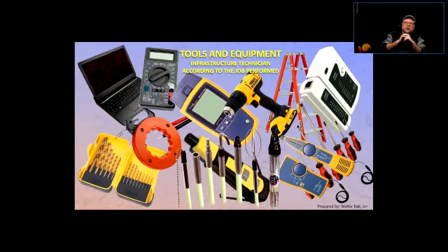Now, when you're talking about bigger holes, like 3/4 of an inch or 1/2 inch, and the concrete is hard enough, then even with a hammer drill, you're going to have some strain. It's going to cause you to use some sort of energy to drill that. So the cordless hammer drill is going to help you with some smaller holes in the concrete, okay, and one or two or a few of them.